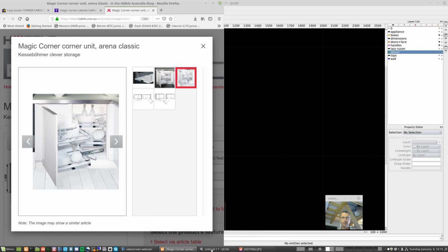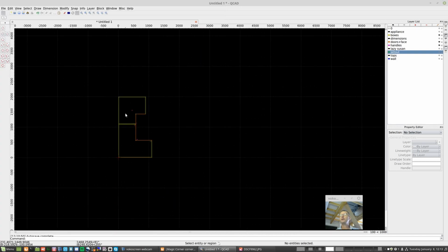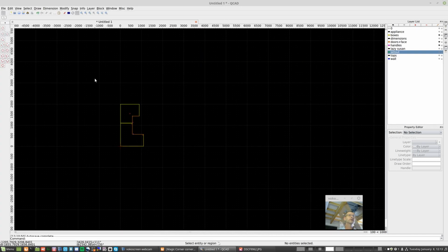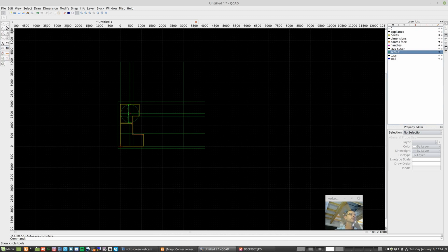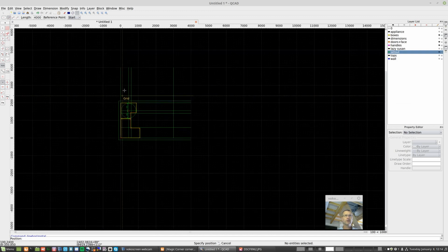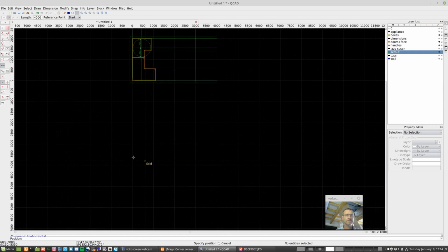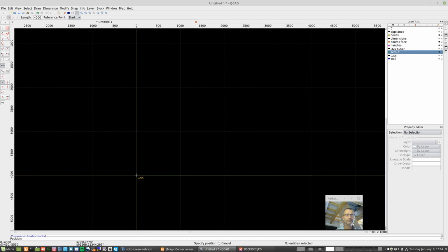So in height, let's just go back to maybe QCAD. Let's draw something front on. Okay, so let's set out, boxes can go back on, oh that is on. Right, let's do that. So now I'm going to draw the set out layer, maybe a side view of a cabinet, let's just do that. So this is going to be like a floor, right? Typical kick might be say 150mm, you can make it 100, doesn't matter, it's arbitrary. You're only talking about a small amount.